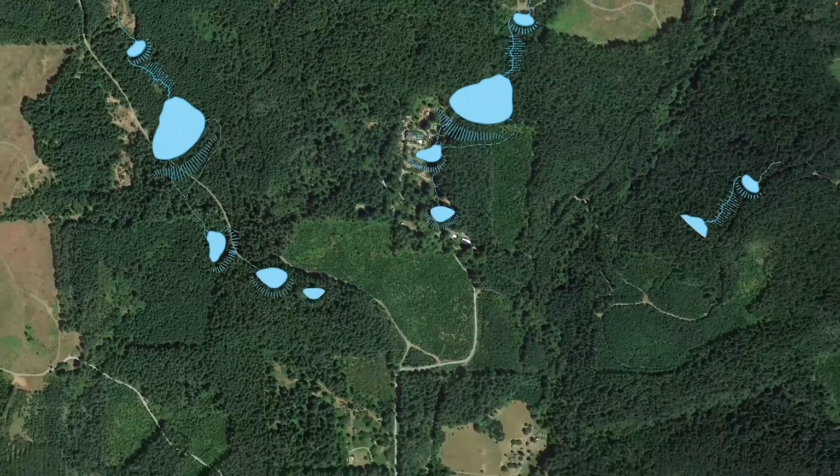It gets built into a trench that crosses all the way across the length of the dam from both sides of the valley. And this is where you put the best, heaviest clay material, and you'll build that key up, starting from that trench all the way up to your desired water level. So the key is a critical element.